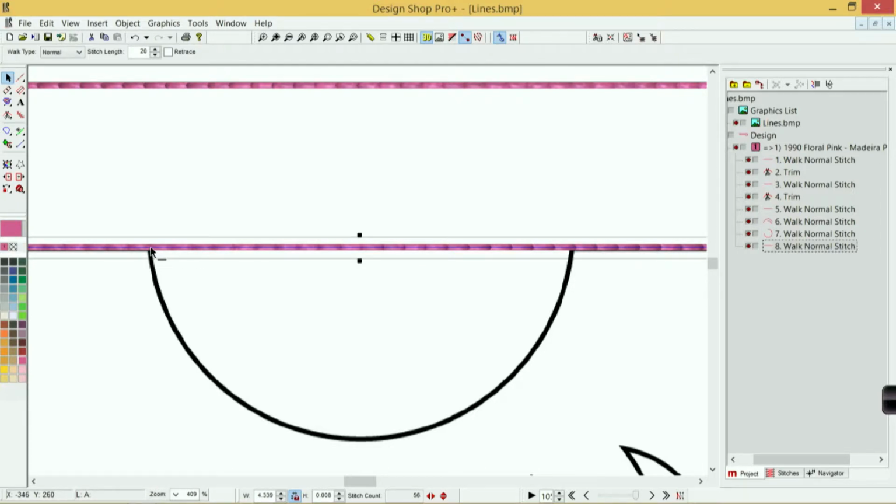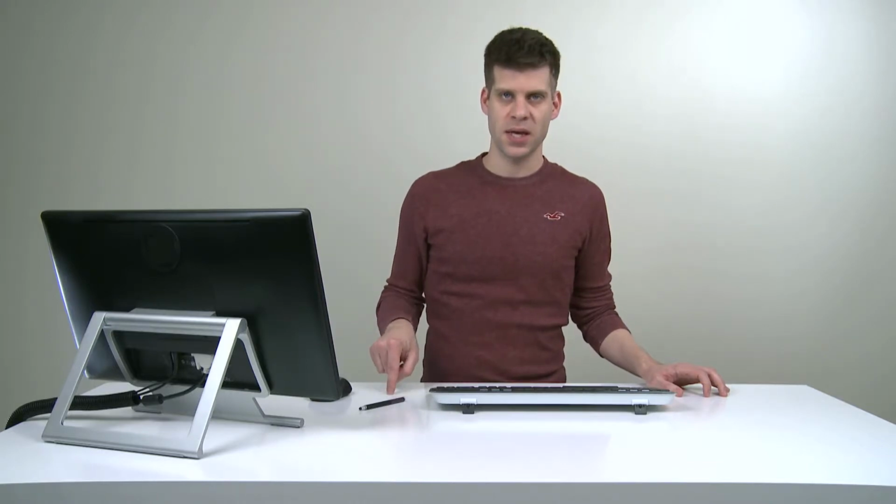So if I go to that transition, I can left click because I want that sharp angle transition. I'm going to do the same thing here. Now watch what happens as I click right here. I've got a needle penetration here, and I've got a needle penetration here, and as I move over, if I left click, my stitches will shift. So whenever you're inputting an input point into an element, whenever you're clicking either a left click or a right click, it will shift those stitches so that a needle penetration always falls right where you're clicking. So that's another reason I want you to be a little bit careful with the amount of input points that you're using. If you use a ton and start to scale them up or down, if you scale them down, you're going to start creating very, very small stitches, and that can be a problem.